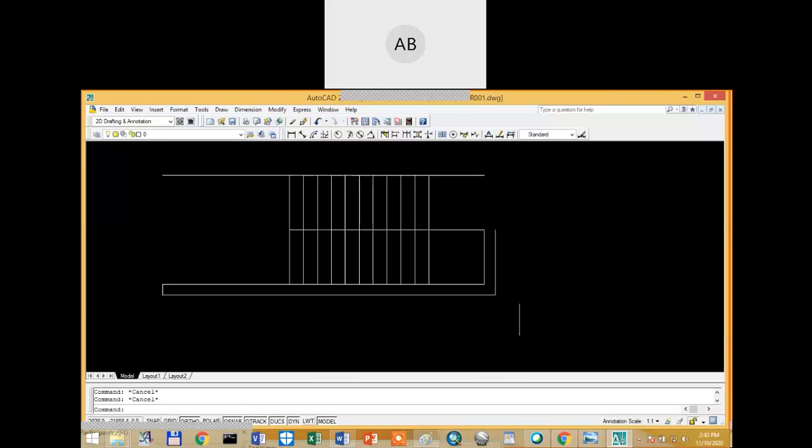So the eye level of the viewer is at the landing portion. So that is why he cannot see these straight lines of the second flight. So that is why in civil engineering drawing you can give a dashed line in this case.